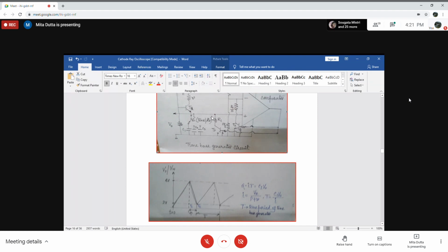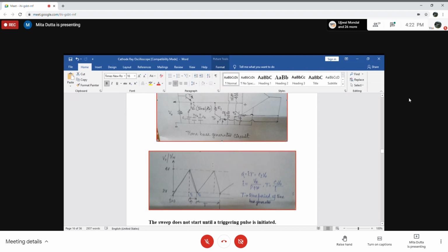So it is marked as the time per division knob, and this voltage is proportional to time, and that is why the voltage applied to the horizontal deflecting plates of the CRO will move the CRO spot left and right across the screen. Now clear how the time-base generator is producing a sweep waveform which is proportional to time.